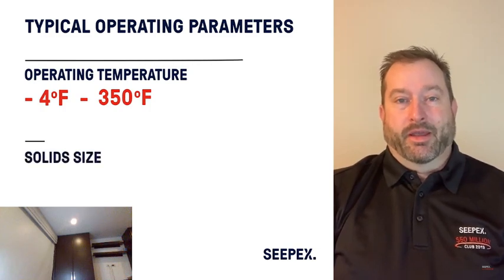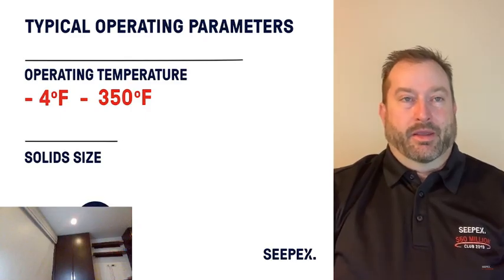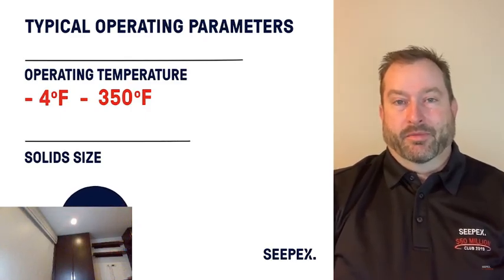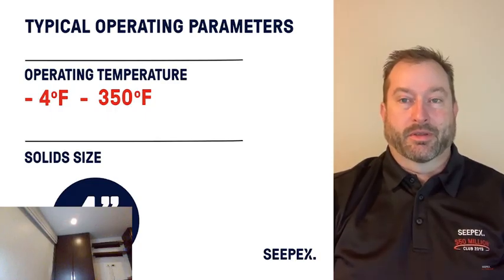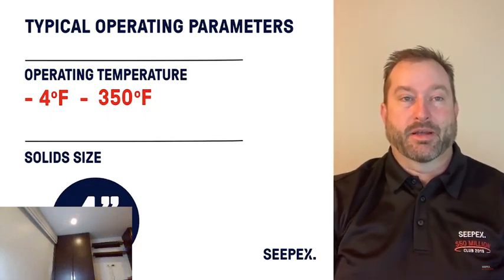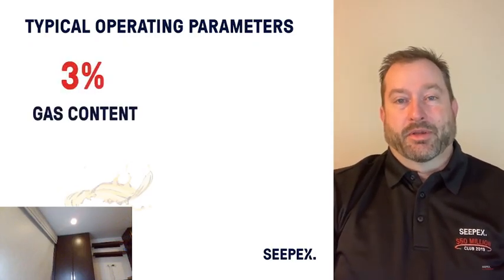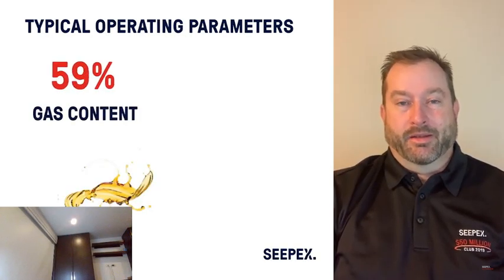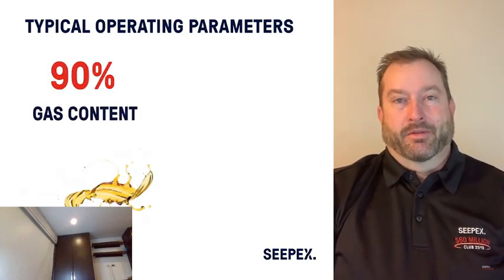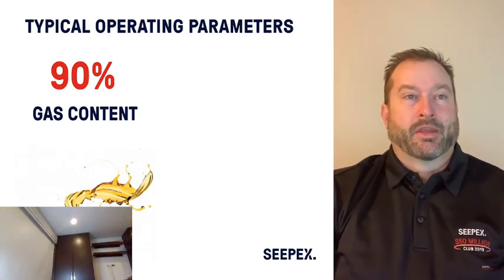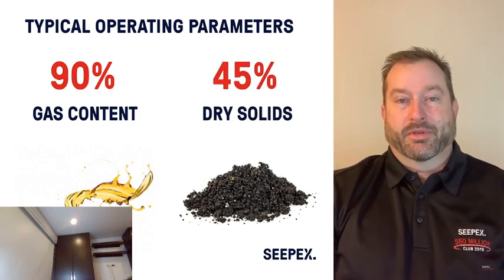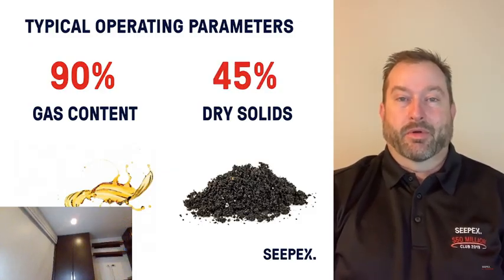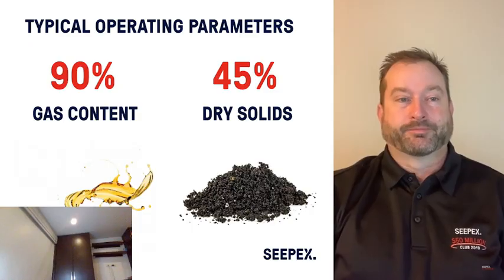Solids, these pumps have the ability to handle extremely large solids. We handle a lot of fluids that have a large percentage of solids, but are very small, all the way up to products that have large, in some cases over 3 to 4 inches size solids. The pump can also handle a mixture of air or gas and liquid as well as solids. So they're pretty unique in that way, that they can handle not just liquid, but a mixture of those as well. We can also handle a large percentage of solids, all the way up to about 45% dry solids, which is like a dewatered cake in the wastewater industry.